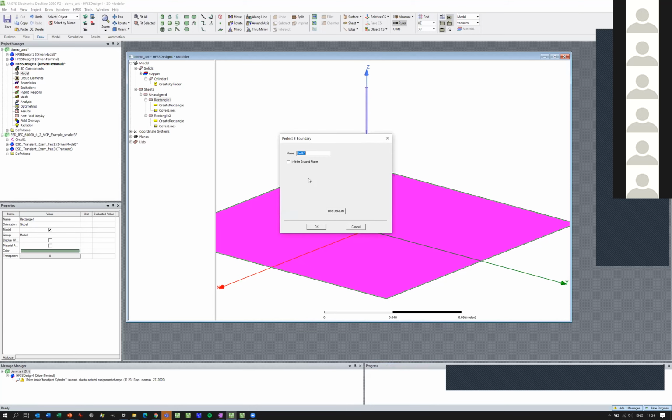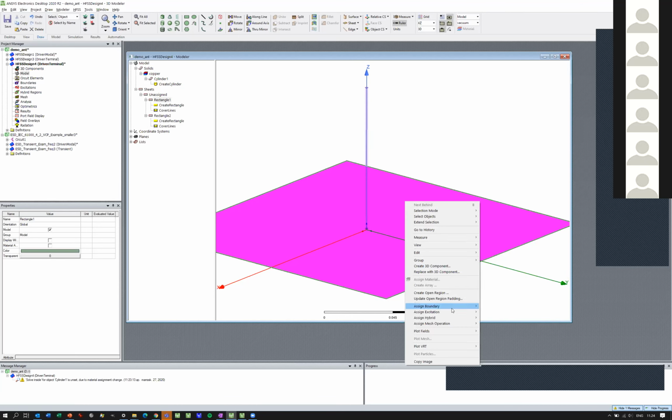So if I click that, and I can say infinity ground side, it means that my ground is a huge layer with this ideal conductor. But let's do it in a more realistic way. So that would already work for me, but I will use a different boundary condition. I will use infinity conductivity.